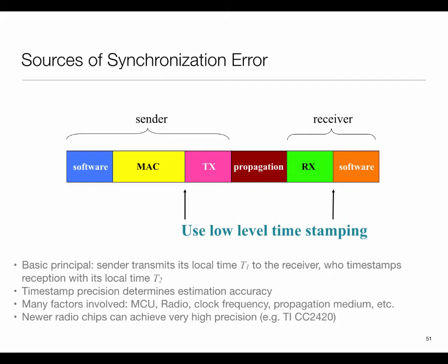And then the only remaining thing you have to worry about is that before the next packet is sent out and that the transition happens again, you have read this thing out, basically, okay. I think we also need to handle the case that we have two separate chips, the RF and the processor. And the clocking you are talking about is which clock? You have to feed the clock from the processor to the RF to take a shadow from it. No. So from the radio or whatever, the transmitter, there is some signal coming out saying, hey, I'm just starting sending the packet, or hey, I just received the packet. Okay, so you take this pin and you tie it to the particular GPIO pin, which the timer is able to monitor. So you will do all the stuff at the processor with the microcontroller level, not the RF.